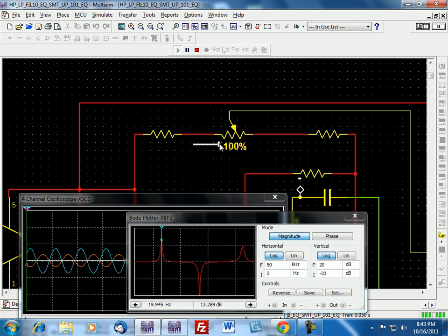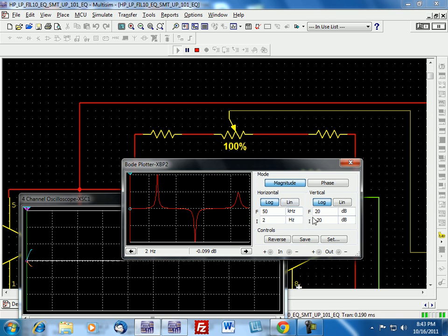I could even go beyond that point, and the higher the order of the filter, the better. And let's see what the boost is on this. Maximum boost is 29 dB, almost 30 dB. It's like a 6th order filter. That's in the boost.